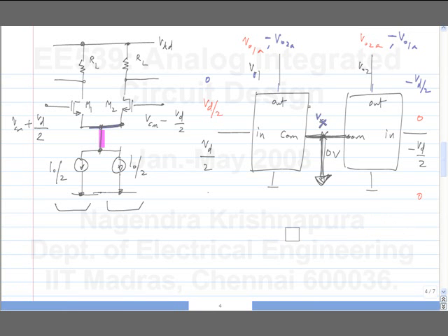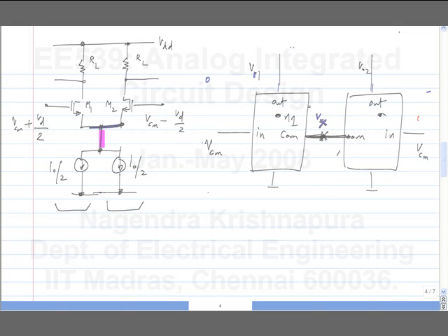So the circuit has a number of nodes internally, but I will just show as one node, N1. And this time around, I don't have antisymmetric inputs, I have identical inputs to the two sides. So that is known as a purely common mode input. That is, there is no difference between the two, you apply identical voltages to the two inputs. So what will happen to, this is not grounded of course, what will happen to Vx, VO1, VO2, all of these things?